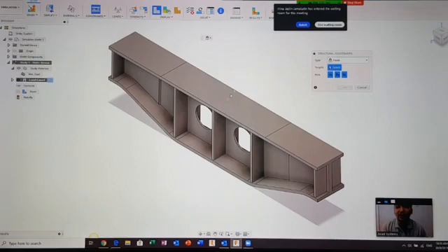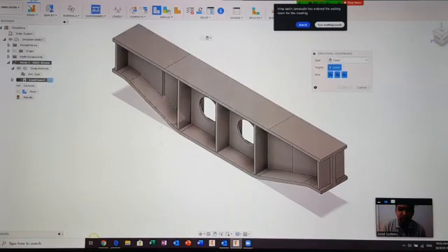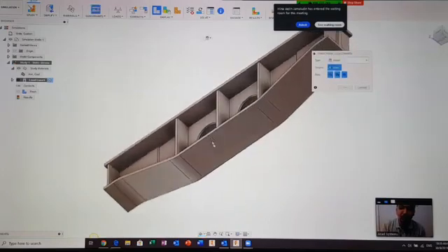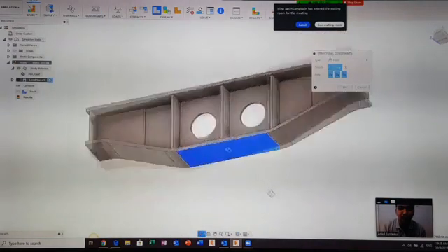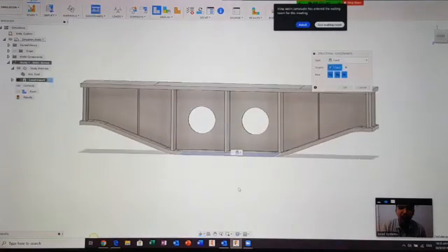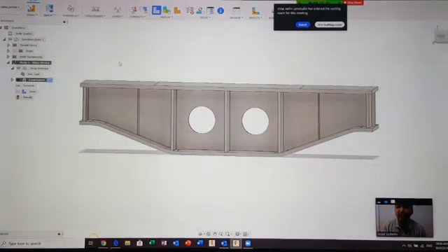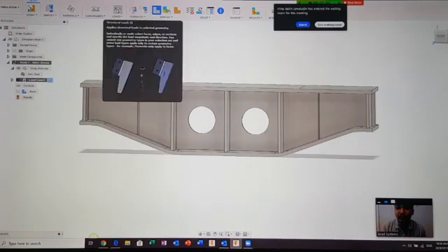Fixed means your location will not move in the X, Y, and Z directions, and also the rotation of X, Y, and Z. So your geometry will be fixed at the location itself. So let's say I'm going to fix here at the bottom the location for stopping or to handle the load from upstairs. Okay, and then now I'm going to put the load.